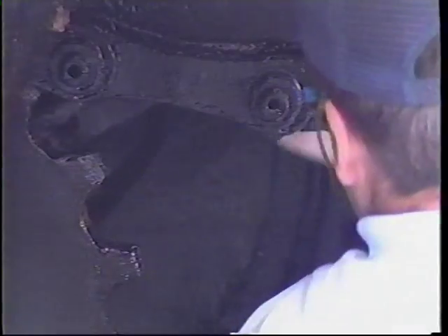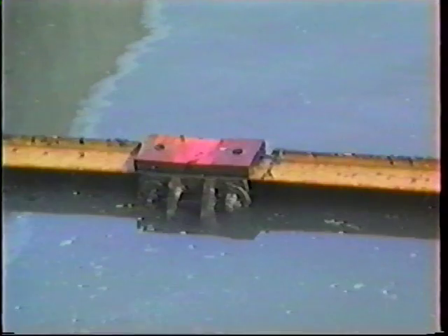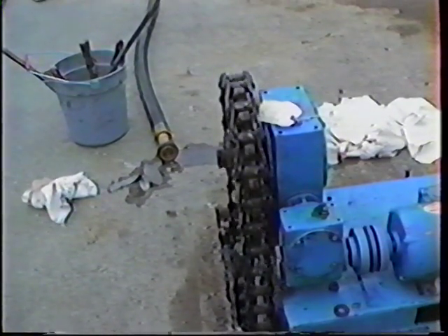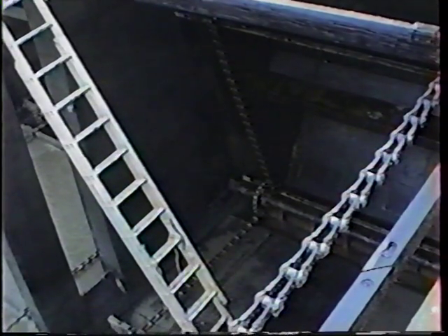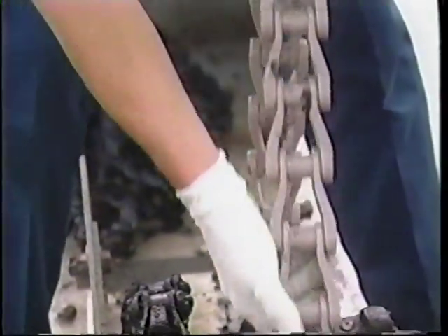Be sure to check the operation of the collection mechanism regularly. Observe the movement of the chain and scraper mechanism. It should be fairly smooth, not jerky. Be sure to look at and note the condition of the chain, wear shoes, and flights. If the motor and the gearbox run, but the collection mechanism does not, it could indicate that a shear pin or chain may be broken. To determine what the problem may be, observe the drive chain. If the drive chain is moving and the collection system is not, it probably indicates a broken chain on the collection mechanism. When the drive chain breaks, it may be missing altogether.